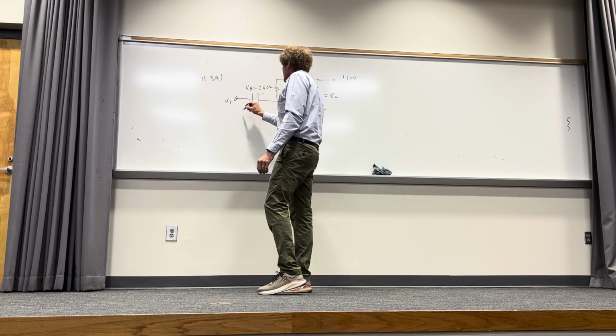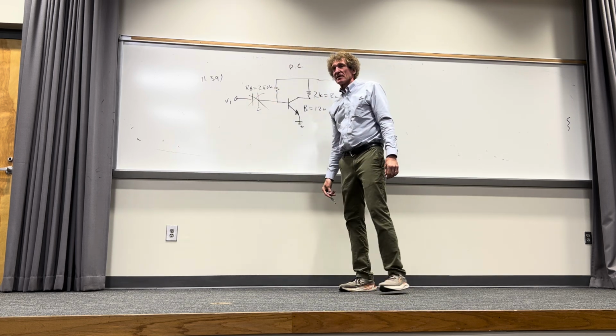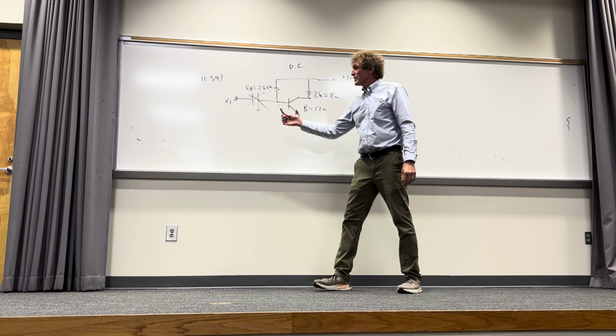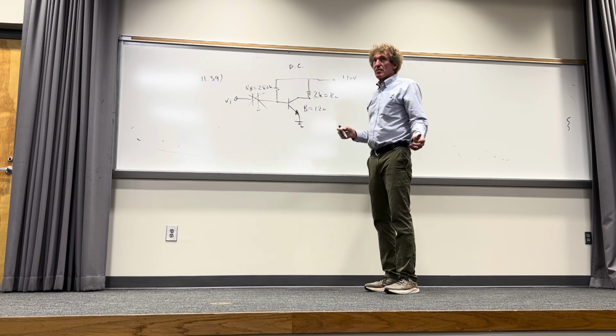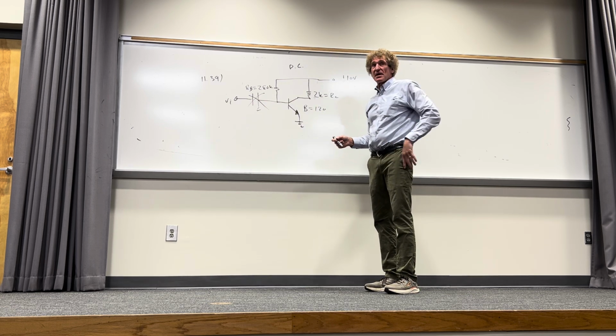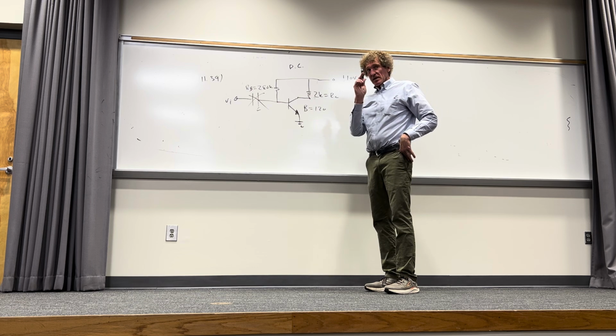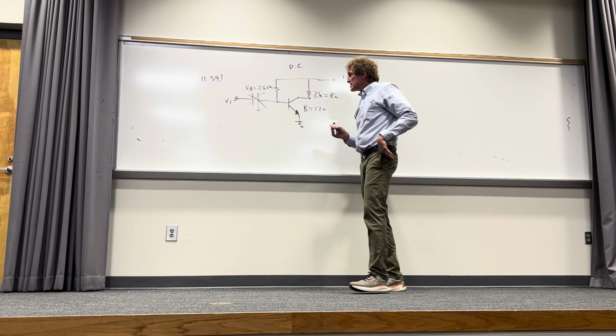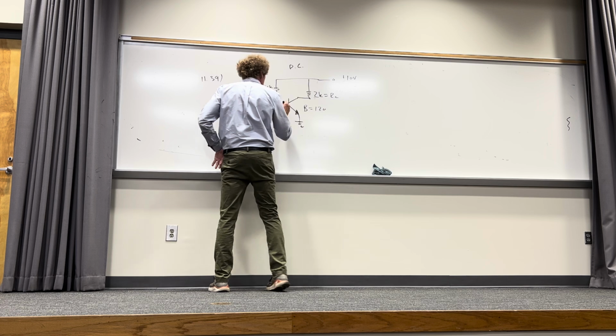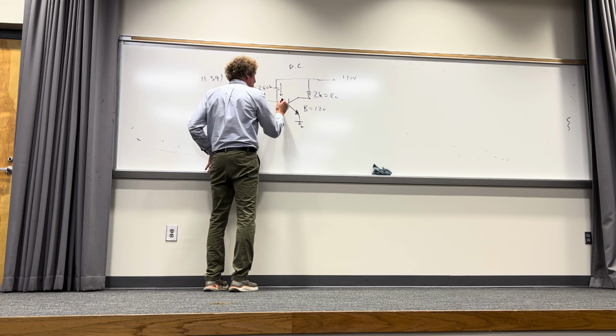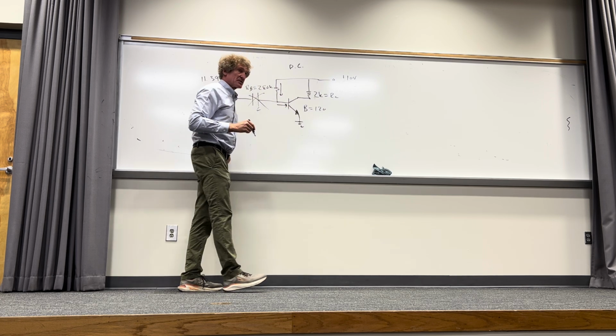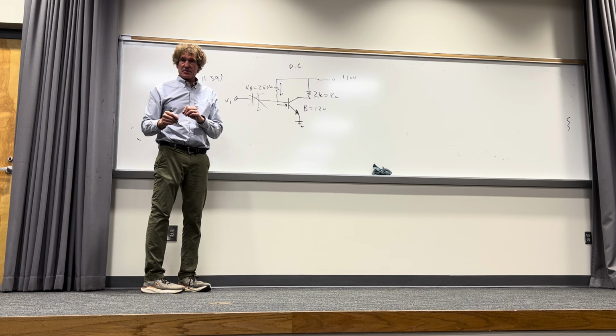You don't even need to consider that here. It's nothing. With me? It'll couple the AC signal when you go through that part of the analysis, but right now it's nothing. So when you do this, now listen carefully because people will mess this up. The current, all the current flowing down here has to go into the base because it can't flow through that capacitor.